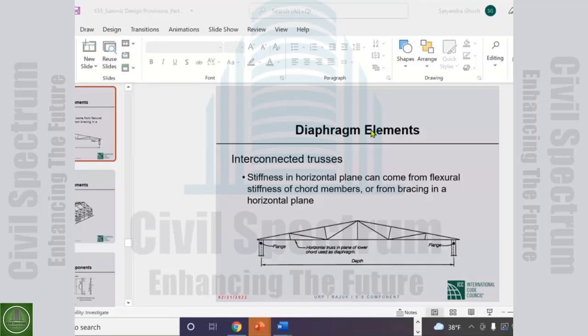Otherwise, you will be designing very weak columns. So the shear in the shear wall is typically quite high in the lower portions of the building. They do require a lot of reinforcement, and there is absolutely nothing wrong with that. It is not the problem of software. That's the way buildings behave.